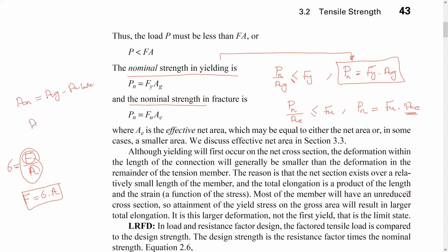Okay, and then we will get the effective net area, which is U times An. We will study this and show you how to get it. Okay, the gross area, which is the section AA in our previous example, is a solid section, we do have no holes. The holes here, it's easy to get the holes, but all the time make sure that you are taking the diameter for the holes, not for the bolt, okay, and we will study this in details later.